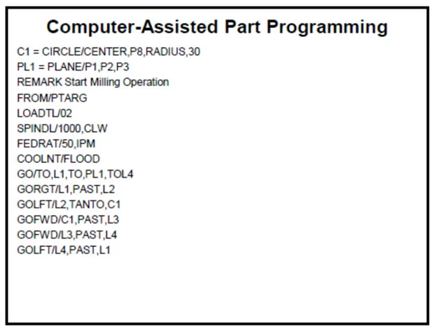For doing the milling operation, first the point has to be specified, then the line has to be specified, then the circle geometry statement has to be specified, then plane has to be specified, and then the motion command has been given here. That is, load the tool number, cutter tool, spindle 1000 rpm, it has to rotate in clockwise. What is the feed, coolant is on, all those commands have been used here for writing the end milling operation. All these commands have been discussed in the previous slide itself.